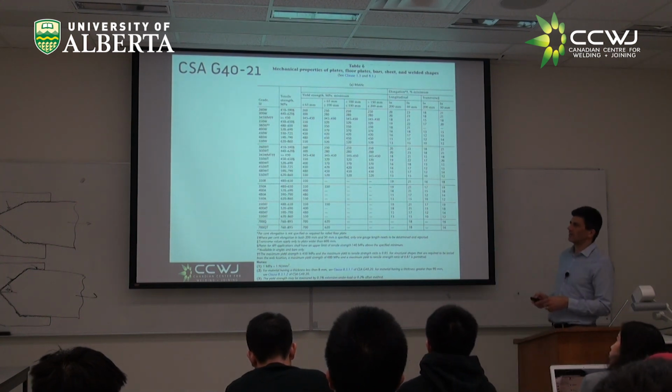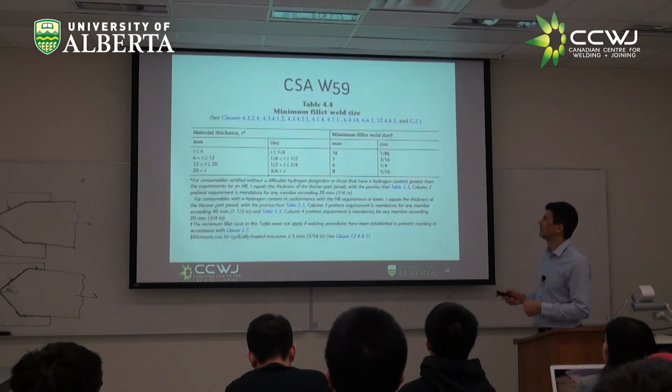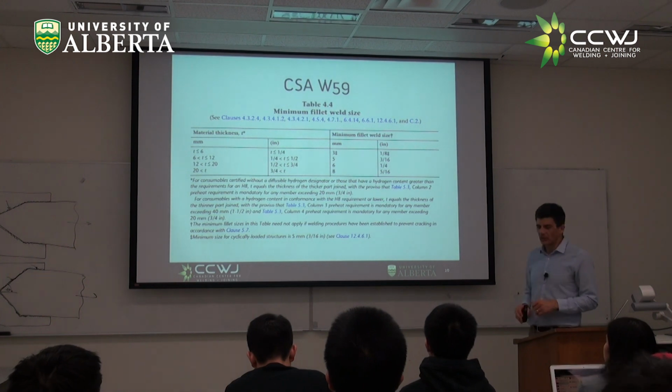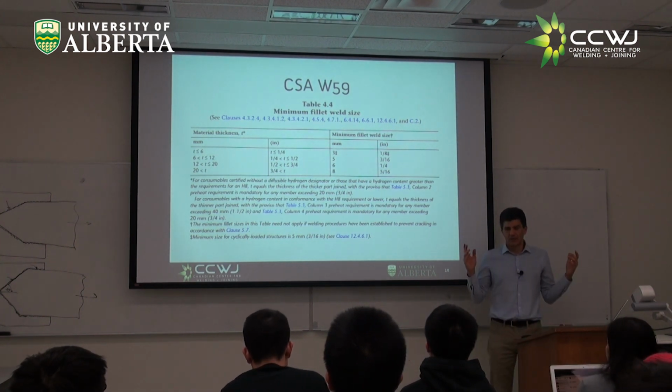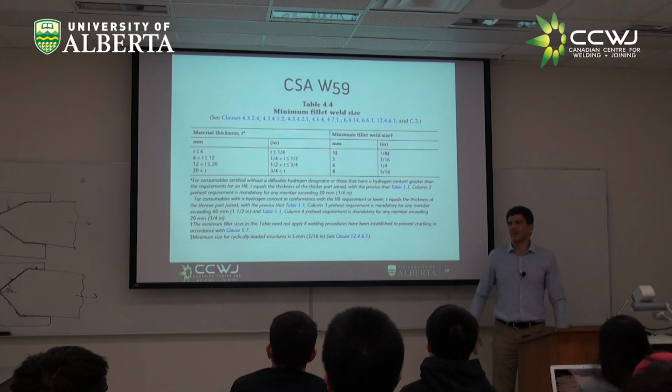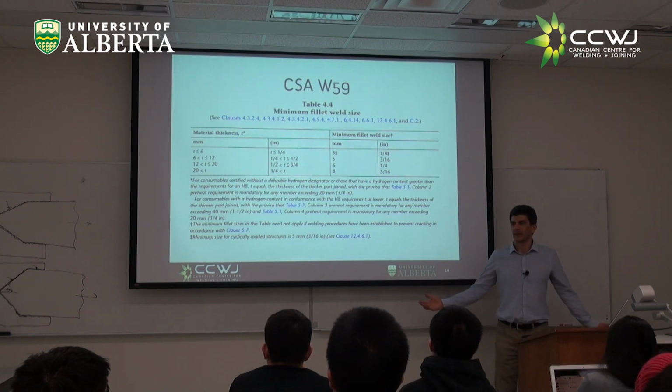And of course, the weld is quite scientific, but there are many things they gloss over intentionally. Here's another thing that is part of the standard. You do your calculation, and you end up needing a fillet of 1 millimeter. Should you do a fillet of 1 millimeter? And the answer is no, because 1 millimeter is too small.